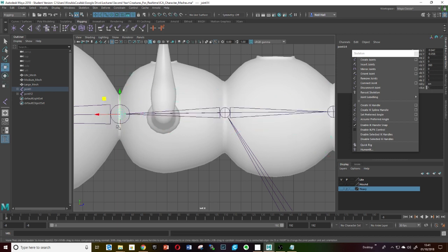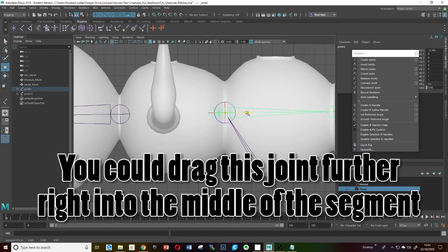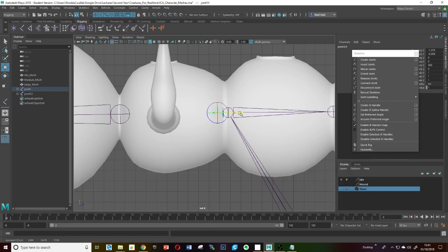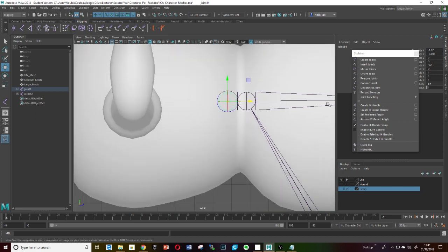If we just select this joint and bring it in a bit, it can be quite close. We might want to move this slightly as well, perhaps go into pivot mode and move these perhaps a bit closer to wherever these two points are. Now, this is really small here. That's not a problem, we can change that in a little bit, but the connection is still correct.